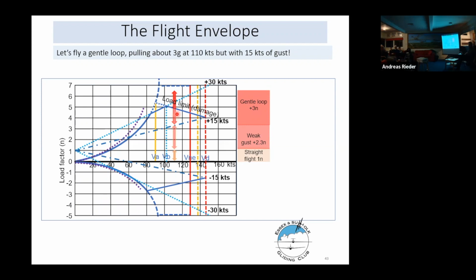of, I don't know, a 7-knot gust, lift of say 5 or 6 knots. So it's not a good idea to be doing aerobatics when there's lots of lift and sink about. We've exceeded our load limit by a significant margin there.